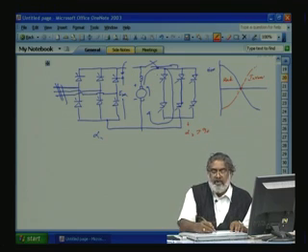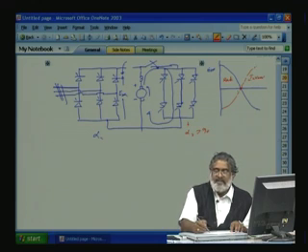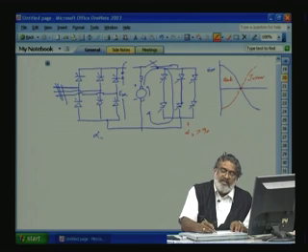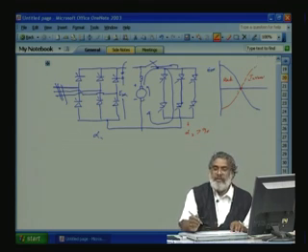So, we can take back the energy here, and once the speed has come to the correct speed, we can slowly increase this one in the rectification mode. Slowly we can increase so that the current from the motor can be made 0, and the moment it is 0, quickly we can open this one and again close this one. So, that way we can control.